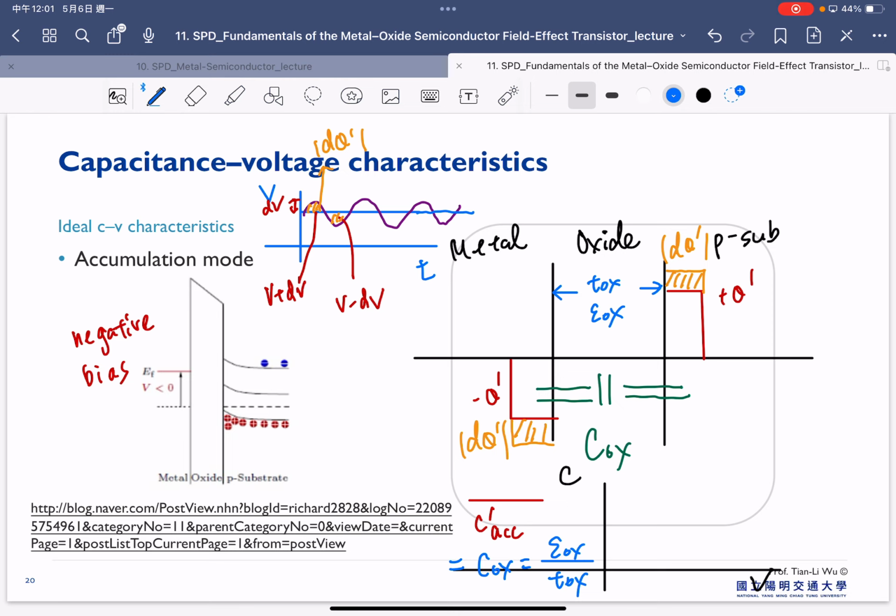So again, just to illustrate the point. We apply negative bias. We already knew there is accumulation of the holes here. So if we plot the charge distribution, we have a negative charge here. For sure, we will induce a positive charge at this point, because we have the hole accumulation. But right now, we consider not only the DC but also the AC signal. So we apply the constant DC, and on top we have the dynamic AC signal here.